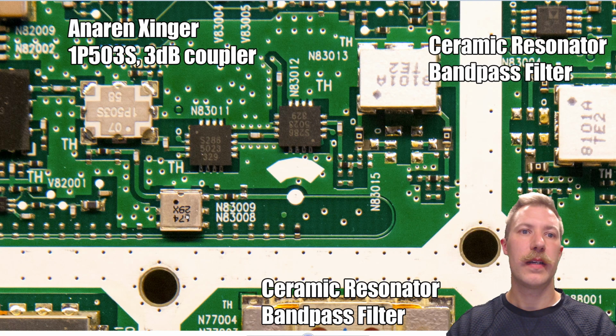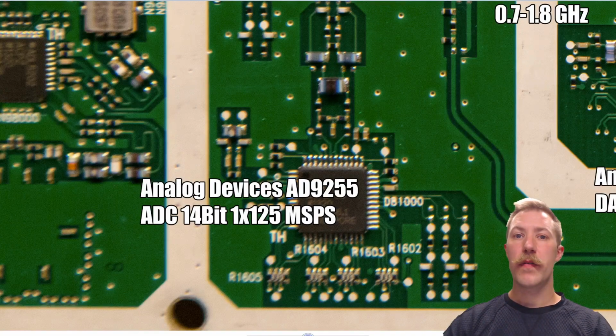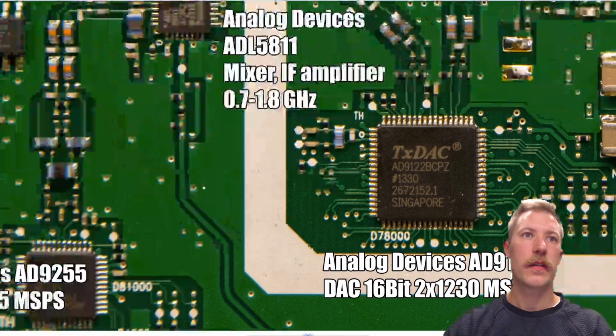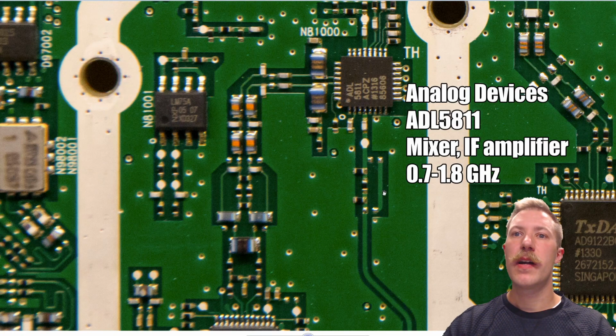One goes down through a, I think that's a ceramic filter, but I'm not quite sure, and down through a grounded line. Then there's two smaller amplifiers sitting in a cascade here, before it goes into a ceramic resonator bandpass filter. One of the receive lines begins its journey over here, where we have the connection to the duplexer. There is a lot of impedance matching along the signal line, which goes up here, ends through a mixer or IF amplifier, where the signal is sampled down to a lower frequency signal.